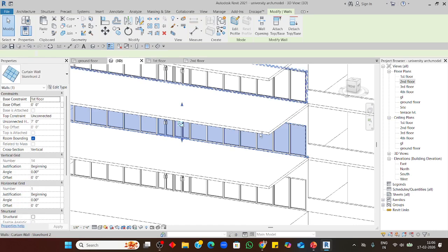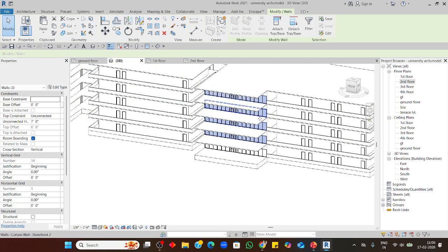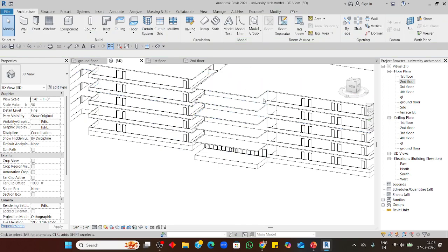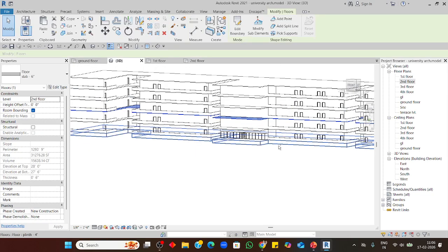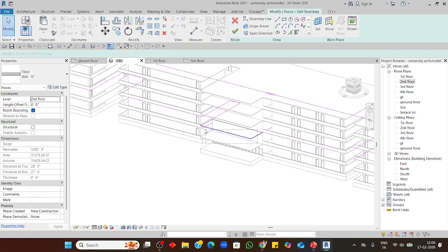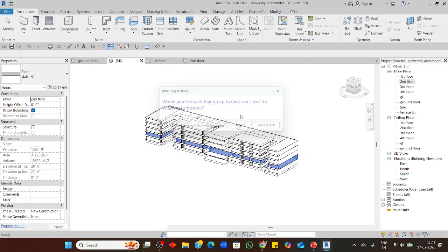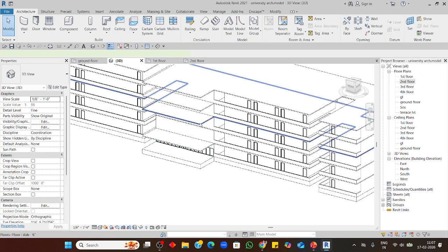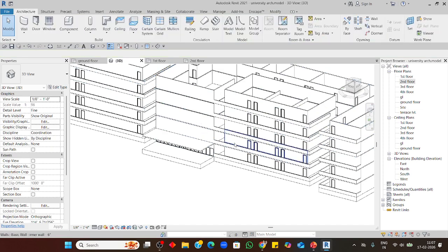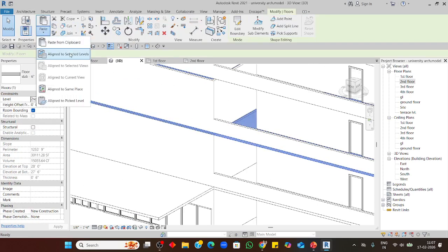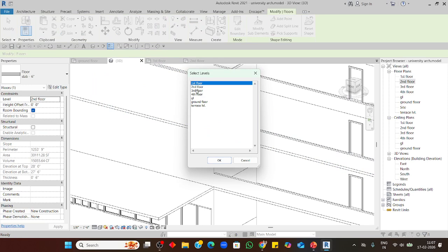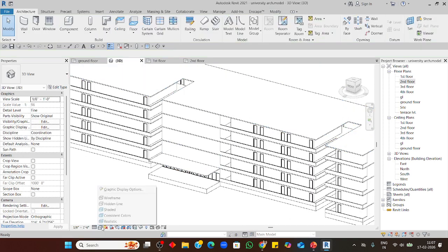So in this plan, there is no this one. It's directly a solid wall. So here the slab is there now. Edit boundary. Select this one. Finish. Now in the same way, we have these three also, delete. Make this slab over there. Copy paste to the second floor now. You have to copy paste to third, fourth, and terrace.